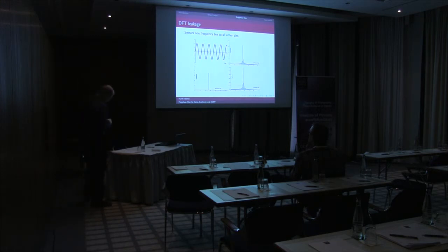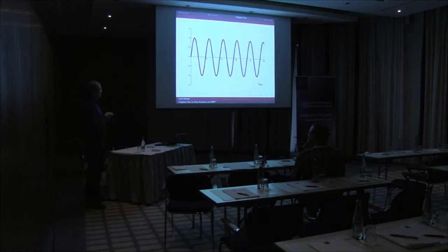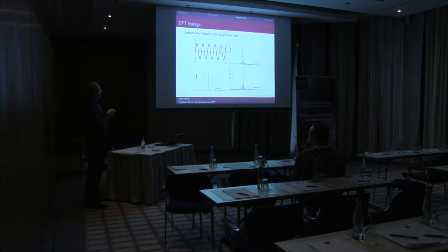Well, I should say it, yes. If you have a frequency in your signal, and it is not exactly in the center of one of the DFT frequency bins, it will get smeared into other bins. Because here the graphs are not very readable.